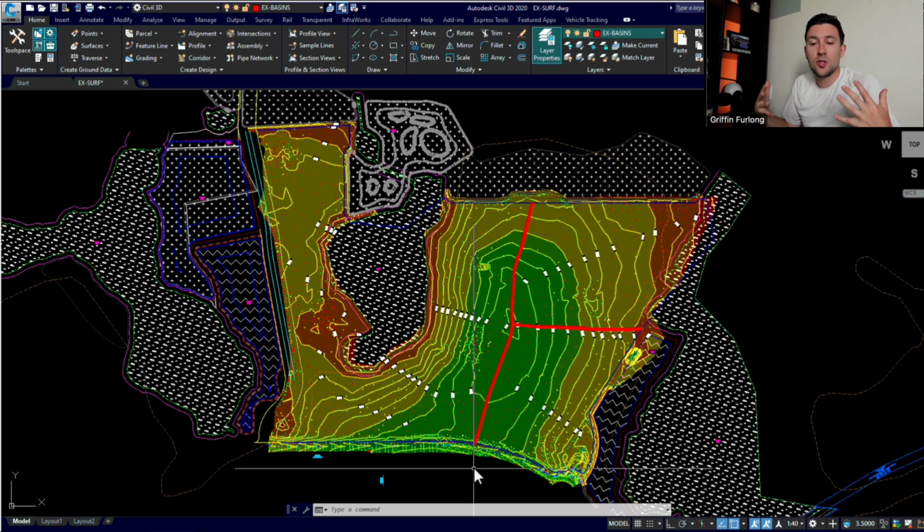In that case, you have a project where you already have a developed watershed, and really at that point, it's up to you, the civil engineer, to just verify that those basins that were developed make sense to your specific site topography that you received from your surveyor. Because some of these watershed models, guys, can be very high level, developed on LiDAR and just the best available information. There's nothing better than getting really specific site survey information.